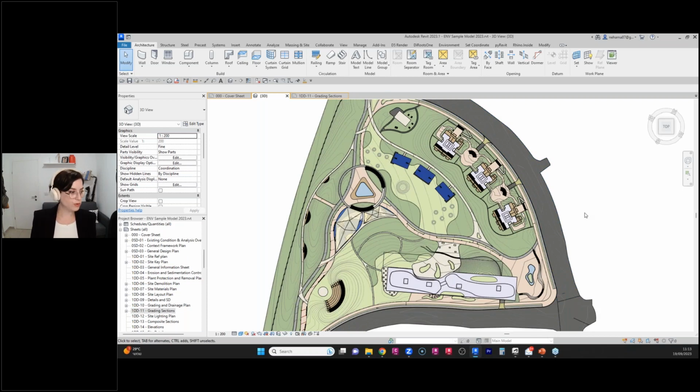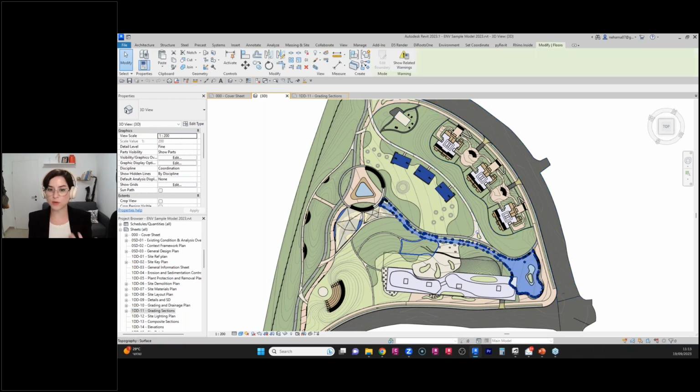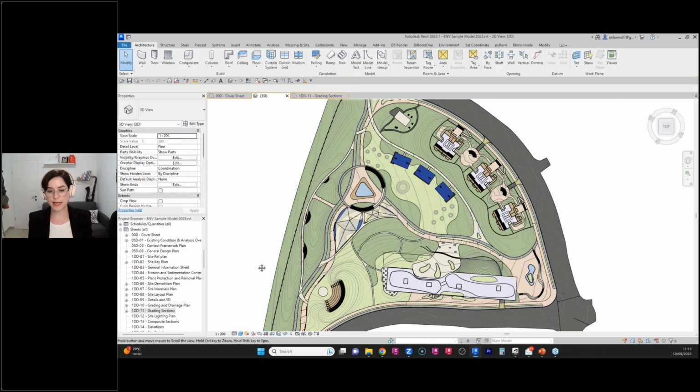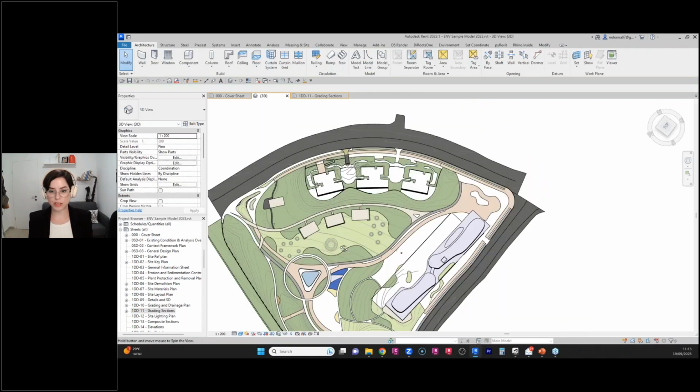plan view, you're used to using flat lines, Revit can be a perfect transition for you because we're always starting with flat geometry. You can either use detail lines, which are just polylines in Revit, or you could straight away start to create these flat floors, flat geometries. And then step by step, we're going to assign elevation to each of these geometries.